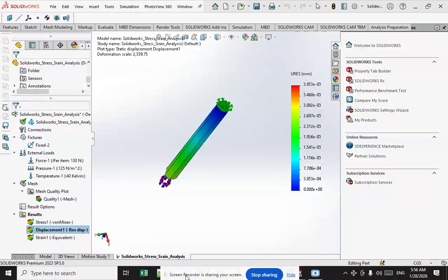These stress fields are often termed hyperstatic stress fields, and they coexist with the stress fields that balance the external forces. In linear elasticity, their presence is required to satisfy the strain-displacement compatibility requirements, and in limit analysis, their presence is required to maximize the load carrying capacity of the structure or component.